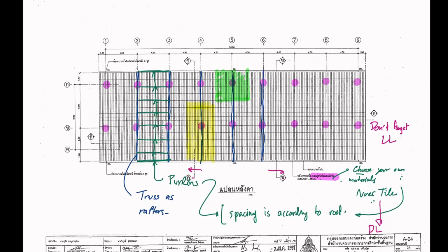Because if you use metal sheet and you don't use insulation, the problem with metal sheet is that when it rains, it's very, very loud. Super loud. You can't sleep underneath it. And say, if you really want to use this as a school and you use metal sheet, when it rains, no teacher can teach. It's going to be super loud. I don't have the English word for it, but it's pretty much like someone banging on a tin drum or a zinc sheet, super, very loud.